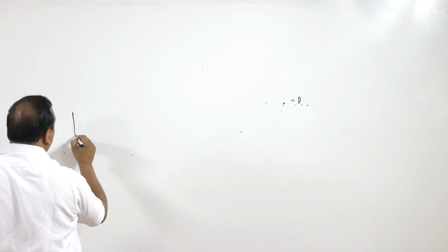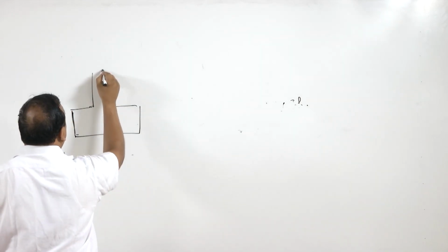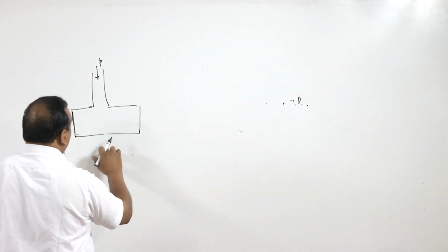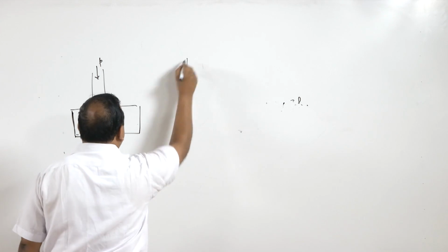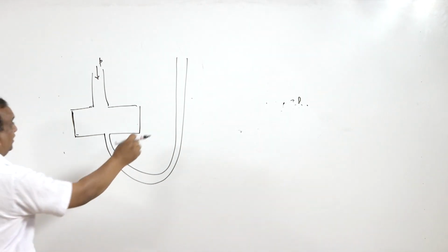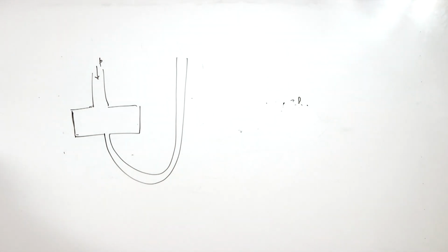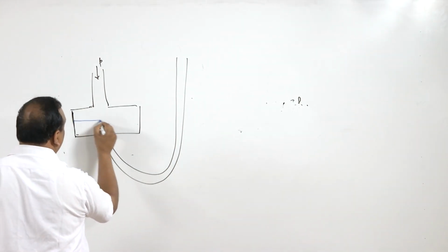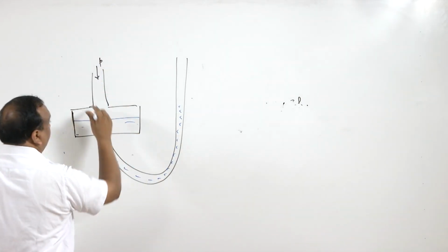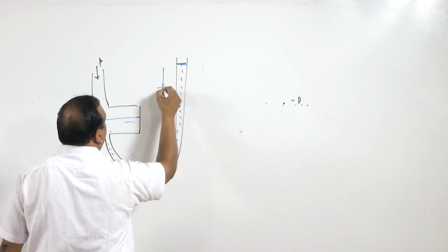In the well type of manometer, there is a well which has a very high volume, and this side is connected to or exerted by a certain pressure. The bottom of the well is connected through a U-tube to a transparent tube which has a negligible, very low cross section compared with the well. Now this well and the U-tube are filled with some fluid, let us say mercury, and because it is pressurized, some column has developed. This is known as H.